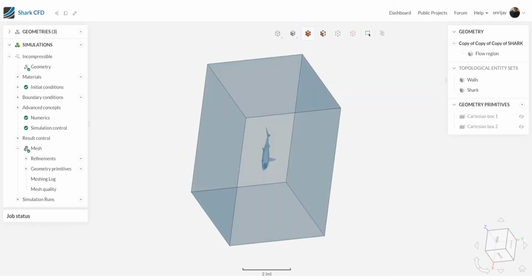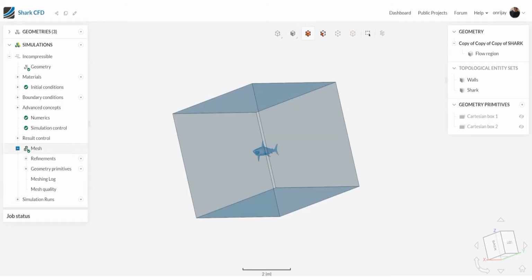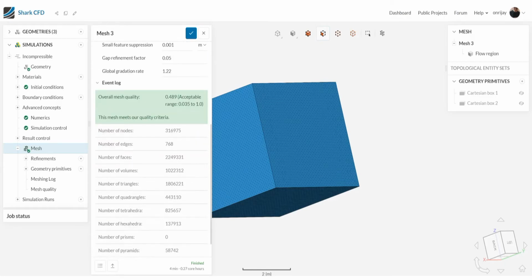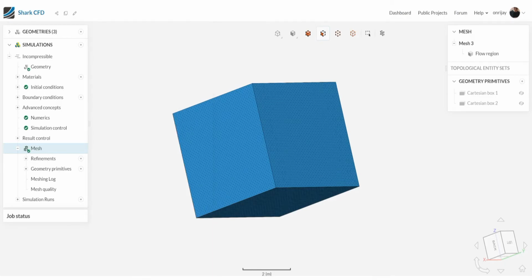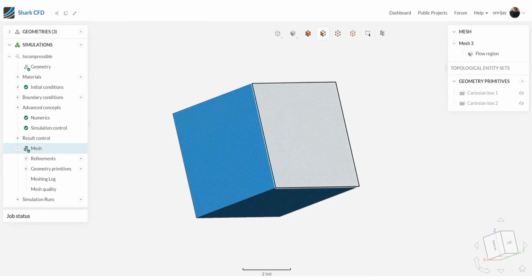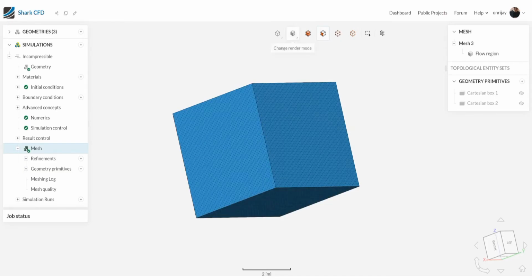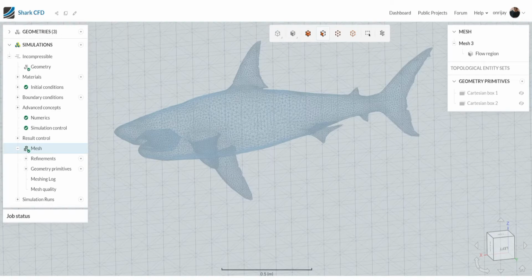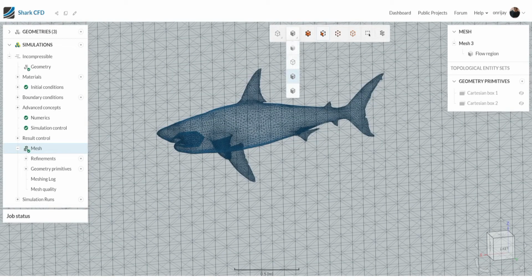It's not necessary. But once we get to this point, once we've generated the mesh, and we say generate the mesh, then you'll see a box here on the bottom. It'll say mesh, create a mesh, and then you select that. It'll calculate how much time it takes to create these 3D shapes. So in our case, let's again choose a translucent surface so that we actually can see the shark in the center here, and that way we don't get lost. So let's do that here. Face, long. All right, the rest is good.